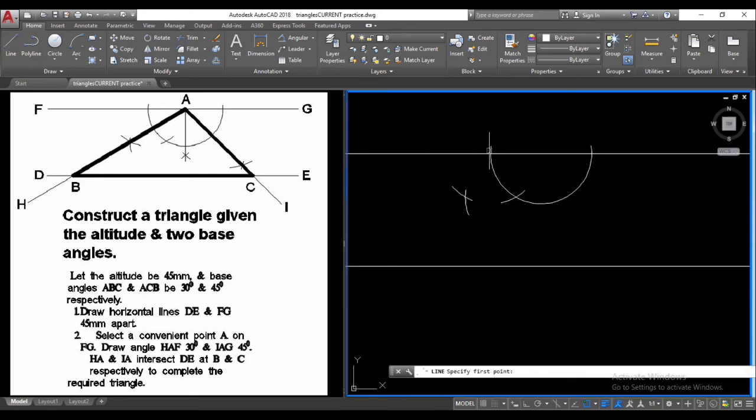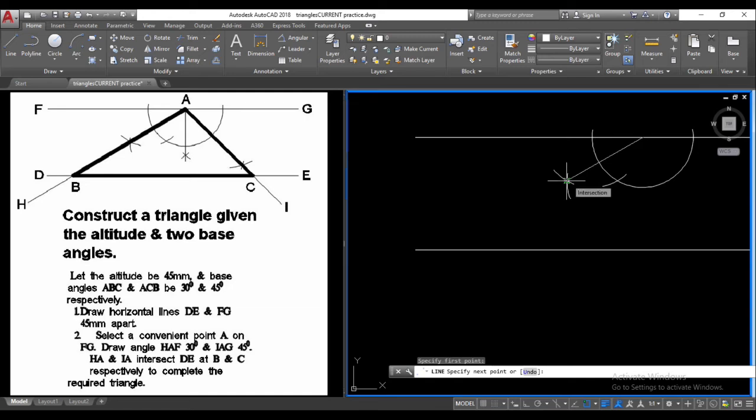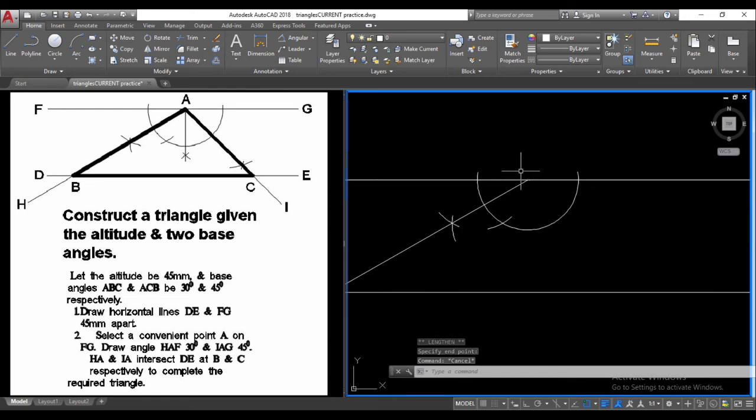So we have constructed a line 30 degrees from point A going through this intersection, and this line to H is now given length, so I'm just going to type in 100 and press escape, and again we're able to lengthen this line if we want by selecting, hover over it and just lengthening to where we want it based on how we like to label the line. On this side now we need to construct a 90 degree angle and then bisect it to get this 45 degree angle here. Repeat the arc tool.